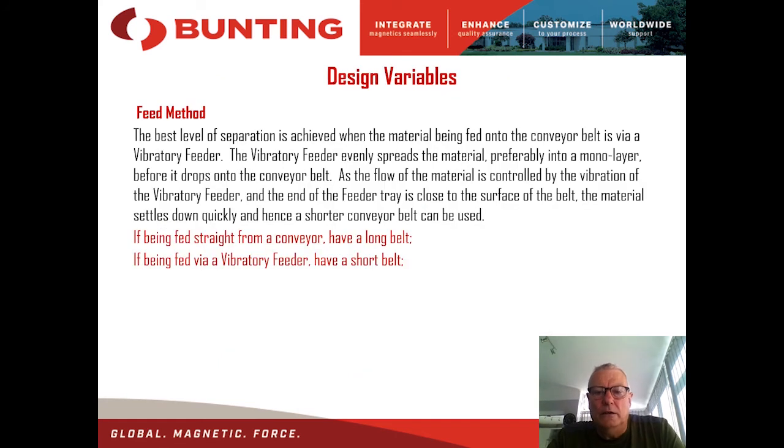Okay, the next design variable is the feed method that we applied to the eddy current separator. As with all physical separation devices, it's essential to have an even monolayer of settled material going into the separation zone of the physical separator, in this case the eddy current pulley at the front. So consequently, this is one of the reasons why we have a long belt feed. These machines tend to have a long belt that allows these ballistic particles, often of quite large material, to feed and be settled before we get into that separating zone.